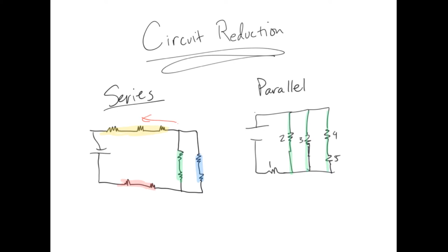So what is the idea of parallel? Well, basically, there's a wired connection from this side of the resistor. Let's call it the high potential side. There is a straight metal wire connection to all the other positive sides of those resistors. And so what that means is that they're all actually receiving the same potential at that location. So the idea behind parallel is that you'll have the same volt drop or potential difference down each branch. So if I compared, let's say, this point here down to this point here, it would have the same voltage. If I tapped across those two leads, you'd get the same voltage as if you tapped here to here.